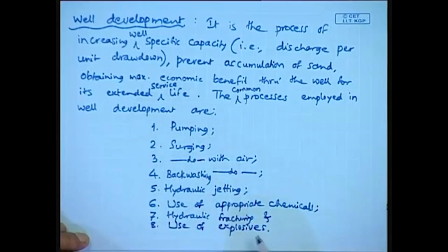So, these are some of the processes which ensure that we can increase, or if not, maintain the initial level of specific capacity, prevent accumulation of sand, as well as obtain quality groundwater for the extended life of a well.